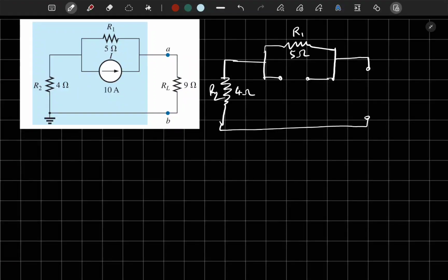So what's the equivalent circuit here? We have R2 with only one terminal in common with R1, right? And this is all open. So we can see that Rn is equal to R2 and R1 in series. So R2 plus R1. And it will actually be like this, Rn this way.